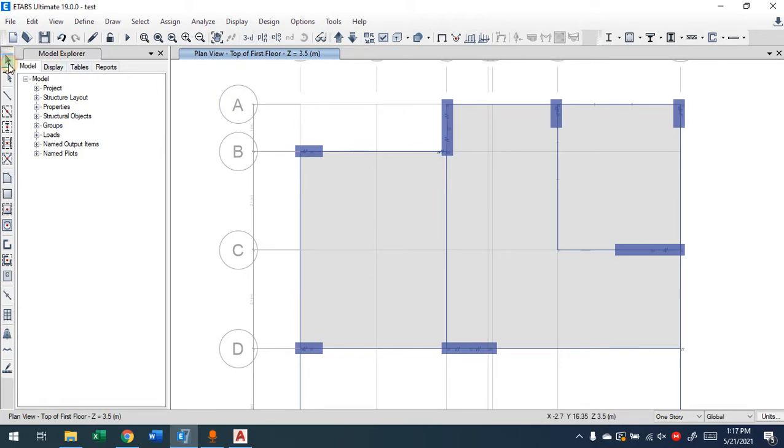So if I click on select here, this is the slab I have here. By the way, I haven't explained this one. Reshape object can now be used for slab here. There are two types of selection here. This is normal select, with which you can select objects. Pressing escape will deselect them. Then there is this one we have here, reshape object. For a slab, when you click on it, it will show you the sides of it.